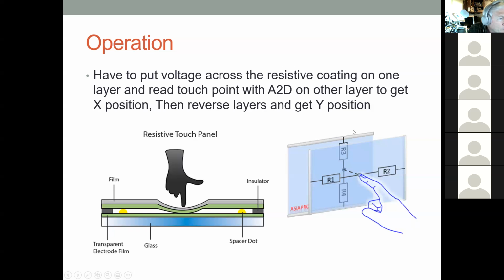All right, so anyway, you get that value, and then you have an X and a Y value. Now, the first thing we do is calibrate this, and we'll go over in great detail how we do that. But once you have calibration values for rotational effects and scaling effects and translational effects, then you get a pretty good readout that more or less divides your x-axis and y-axis into even increments and keeps them in the right planes, no rotation.